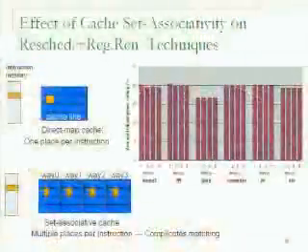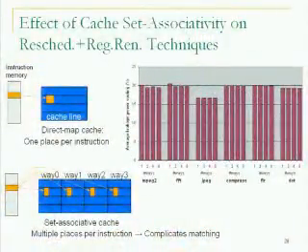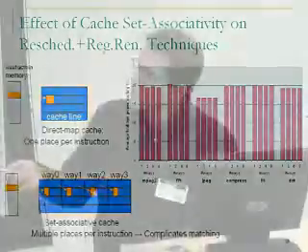But for FIR, again, you see that not much difference happens. On the effectiveness of techniques 1 and 2, since in a direct map cache you have a one-to-one relationship between each instruction and the cache memory, the technique can be much more accurate. But in set associative caches, for an n-way cache, you have n different ways.